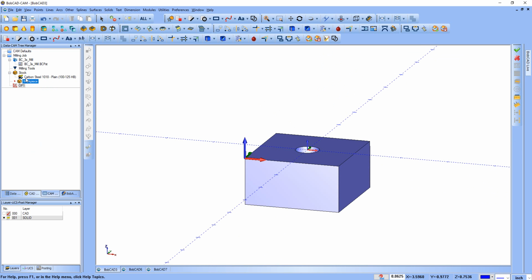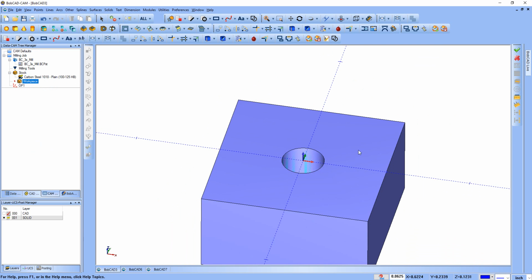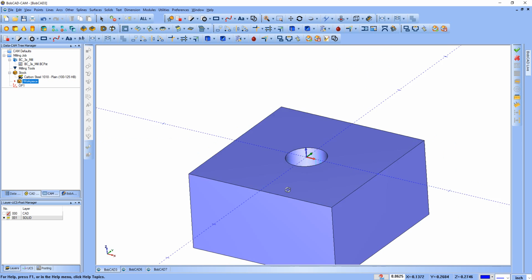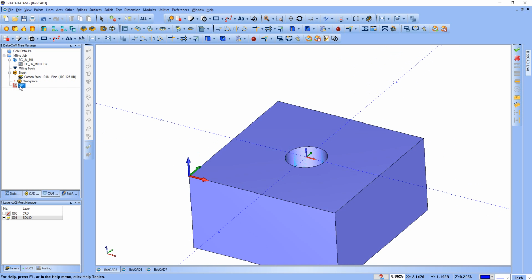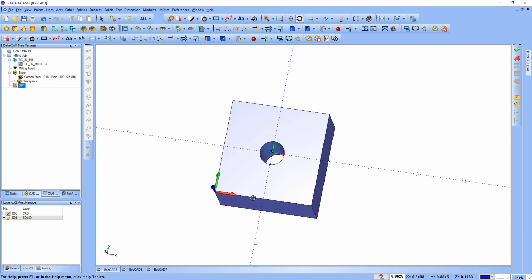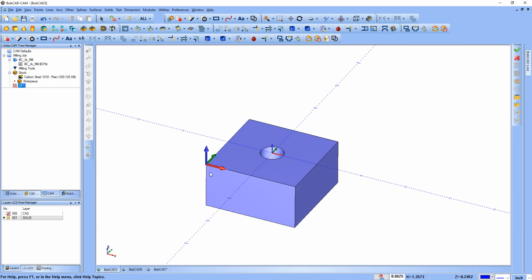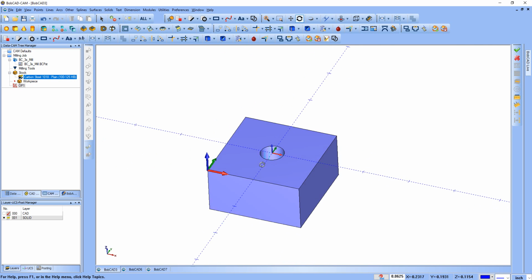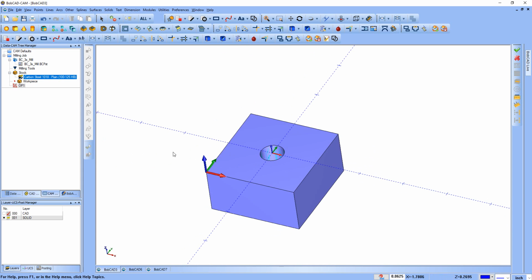So from there, now if you have clicked off of it, I know people have definitely got confused, and I think it confused me a little. This is no longer your work coordinate. What you're seeing there is irrelevant. When you click on this and have it highlighted, it'll show you that's what everything's going to drive off of, all your geometry when you set your toolpath. So I recommend doing these few things before you start doing all your toolpaths, because if you do toolpaths and then move it, it can kind of jack you up, and you may have to run through and reselect geometry.